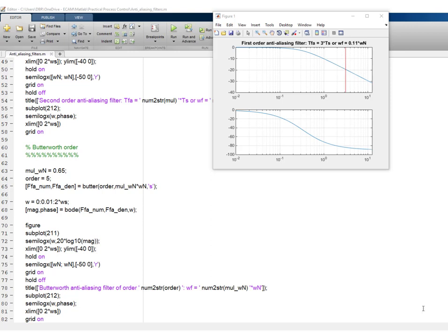We would like to implement, of course, the perfect anti-aliasing filter, but it is impossible to implement such an analog anti-aliasing filter in practice. We will see later that we'll also sometimes have to implement a digital anti-aliasing filter. This is when we change the sampling frequency, and even in this case the order is restricted because this would lead to numerical problems if the order of the Butterworth filter is chosen too high.